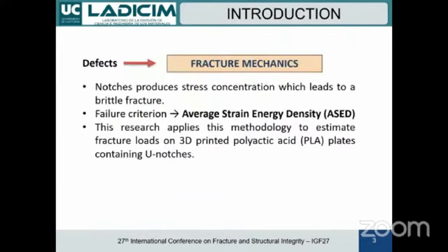Well, as you know, notches produce a stress concentration which leads to brittle fracture. In this case, we are using the average strain energy density as a failure criterion. In this research, we applied this methodology to estimate the fracture loads of 3D printed PLA plates containing U-notches.